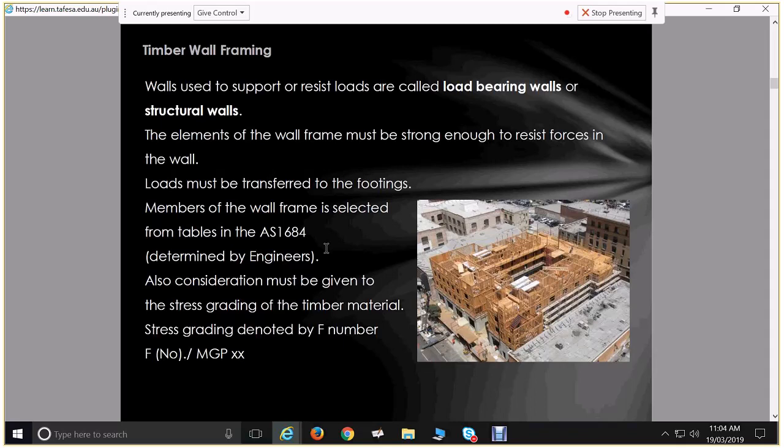So there's some species of timber or timber grown from a particular tree which is going to be stronger than another one. If we have timber grow really slowly, let's say we've got a piece of radiata pine. Pinus radiata, that's the most common pine that we go building with in South Australia. We've got stacks of that growing down in Mount Gambier. Let's say we've got a piece growing in Mount Gambier and we have a piece growing in the Adelaide Hills here. It's going to end up like a tree, and we chop those down, we're going to have a different stress grade for both of those, the timber that comes out of either one of these. The one that grows slower is going to have smaller grain, and typically is going to be higher stress grade.